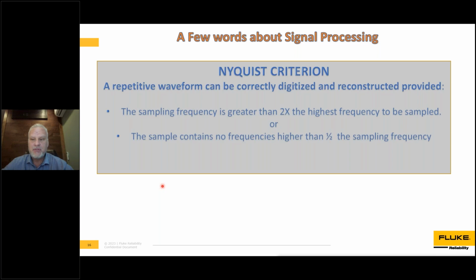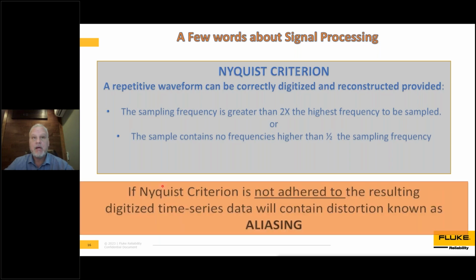With accelerometers, I'll remind everybody, we know what frequency response curves are, but just because a sensor only goes to 5,000 hertz frequency response, that's just its linear range. I'll promise you it will detect things at 10,000, 20,000, 30,000 hertz. All that data will come down those wires into that digital data collector, and if you don't properly filter for this, you'll be in trouble, and we'll talk a little bit more about that.